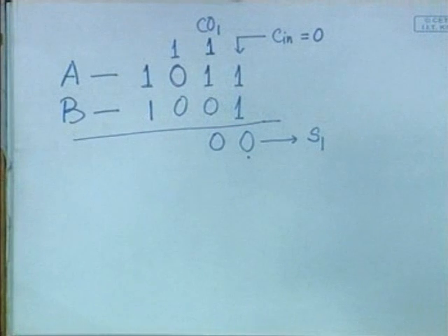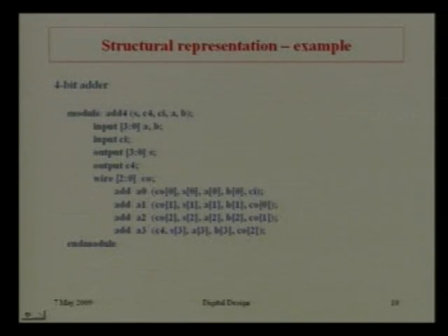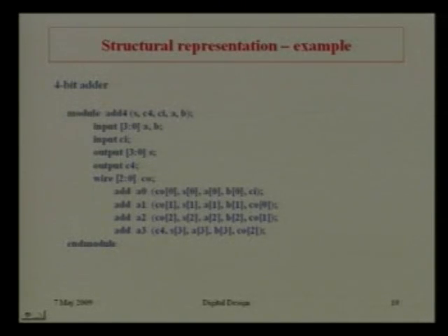So for that, what we have done, the input is [3:0] AB, just like your array. In your C programming you use an array, and this is almost the same type of structure for a 4-bit value. If you want to do it in C, you need a 4-bit array. So that is a similar type of thing they have done. This type of syntax is available. So this is 4 bit. Then the input is CI, which means unless it is specifically told, it is only 1 bit.